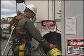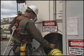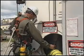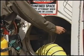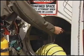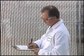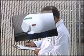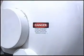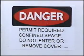Use an approved analyzer to make sure the oxygen level is at least 19.5% before you let anyone enter. Check the air above and below the entrance and around the interior. Do this from outside, and continue to monitor the inside atmosphere until all workers in the confined space leave. To work in a confined space, you also should have a confined space entry permit. A confined space with potentially hazardous conditions such as atmospheric are known as permit confined spaces. And you should also follow all other safety regulations.